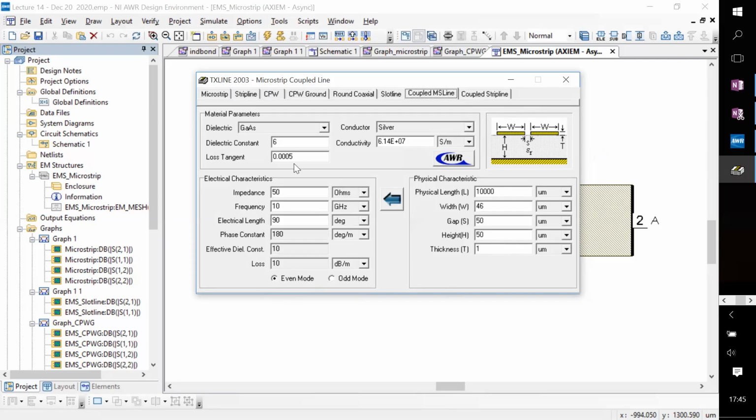So let's set up our standard enclosure setting, 762. Thickness here, we can go back to 35 microns because these are going to be big structures. And width. So if you remember that for 50 ohm microstrip line, you needed something which was about 1,000 or 1,100. So we'll just start with something close to that. Let's say it's 1,000. Both of them are 1,000. And start with something, say, quite big, 500 microns.